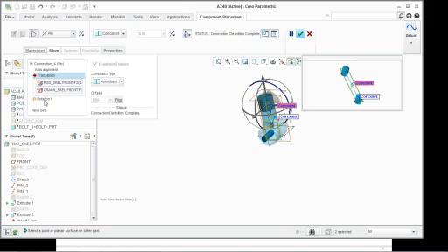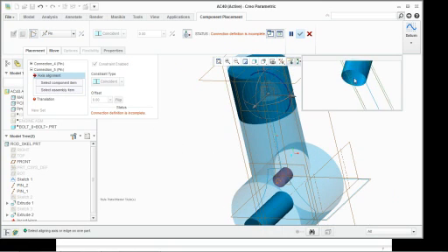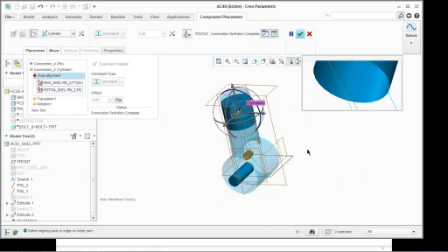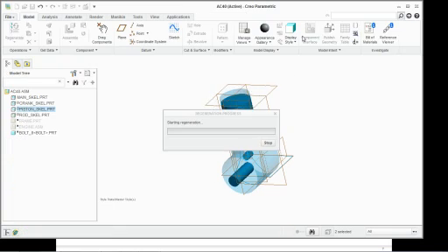And then we're going to go into our placement tab, click New Set. We're going to select, change it from a pin type first to a cylinder. We're going to pick this axis here and that axis there. Notice it did snap those together, and my little 3D dragger has been all grayed out. I have no more degrees of freedom that I can use on that. Well, I have one, but that's just the degree of freedom of the mechanism.